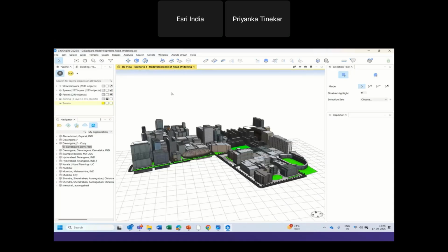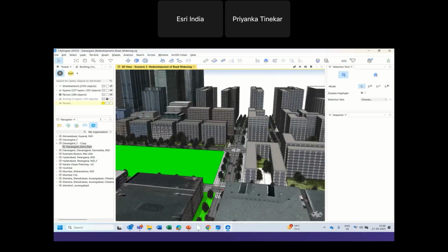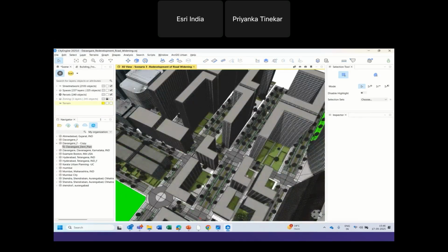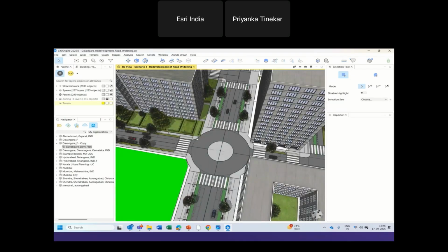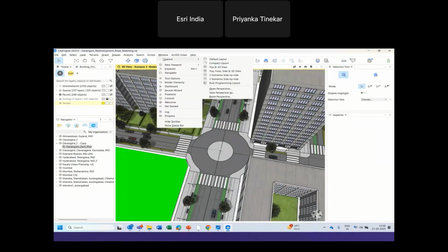So you see here, we'll zoom into the new area and we'll see how it has come up. Now, in regards to this newly redeveloped area, I want to talk about the mobility and transportation aspects. Here the new road hierarchy has ensured smoother traffic circulation to support cycling and walking. Then there are wider sidewalks, barrier-free crossings, and improved street connectivity that enhance walking and access to public amenities. Then there can be redesigning of intersection junctions and transit corridors that can help prepare the area for future integrated public transport, reducing dependency on private vehicles.